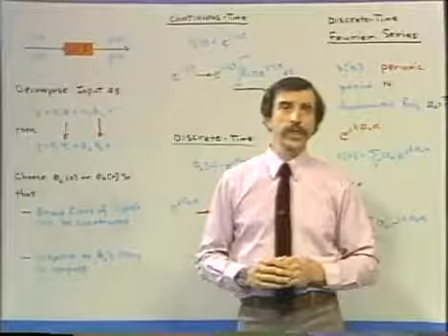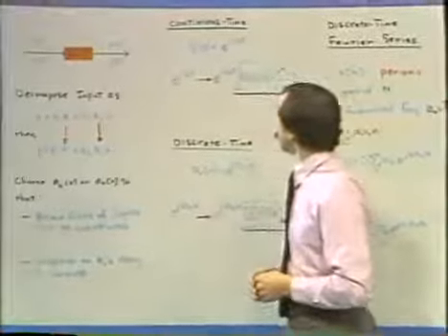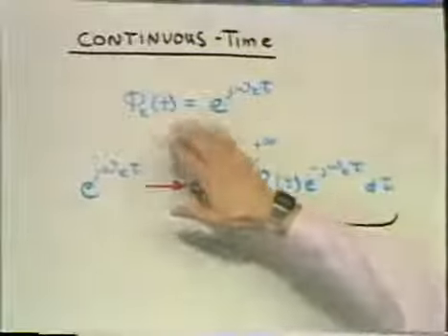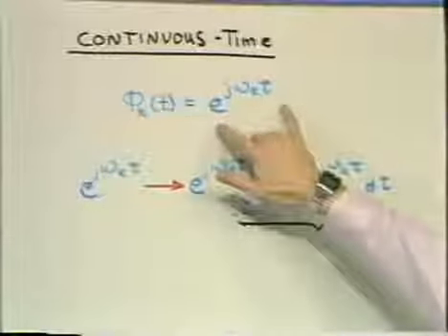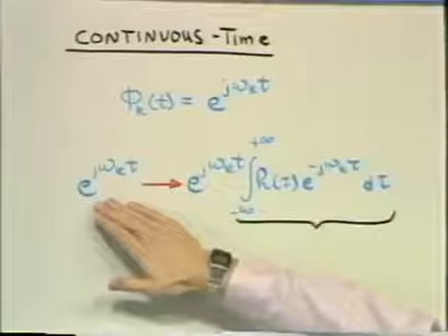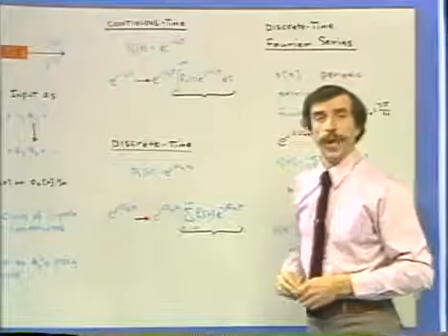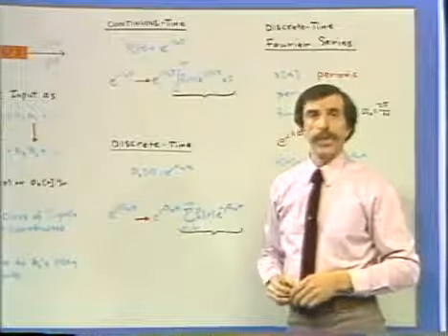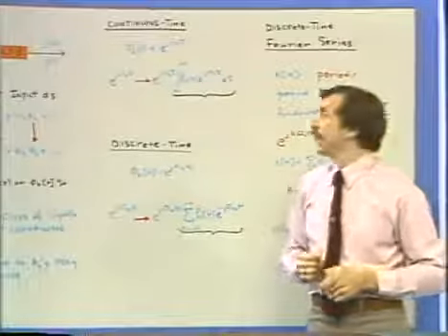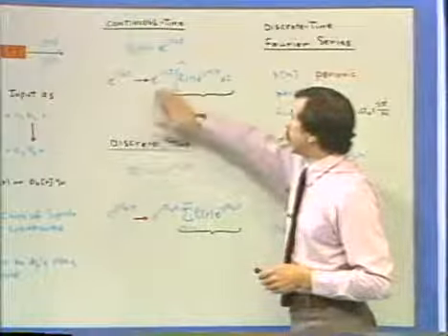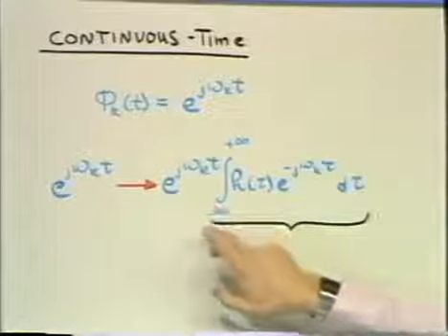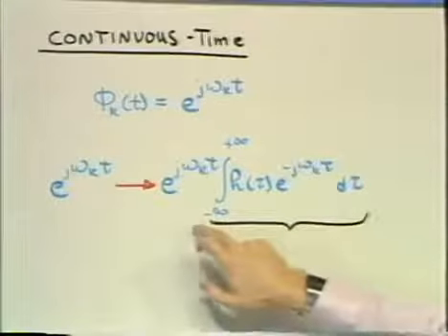And then in beginning the discussion of the Fourier representation of continuous time signals, we chose as another set of basic inputs complex exponentials. The motivation there was the fact that the complex exponentials have what we refer to as the eigenfunction property. Namely, if we put complex exponentials into our continuous time systems, then the output is a complex exponential of the same form with only a change in complex amplitude.